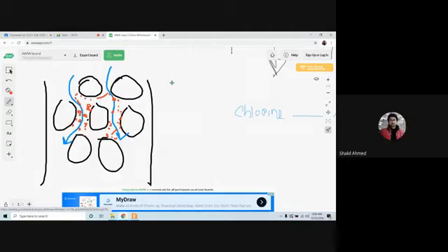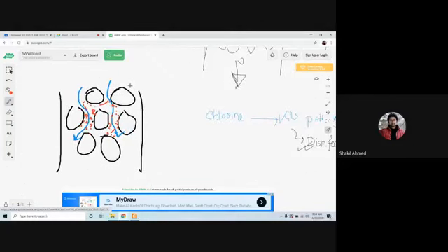Yes, sir. You have to wash out the filter media because this filter media will eventually be clogged with time by the deposition or settlement of the particles or pollutants. What you can do is bring up these gravels or filter media, wash them thoroughly and put them back. Okay. Yes, sir.